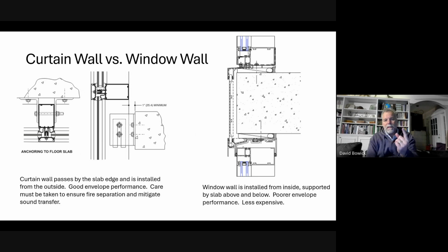You see the upper glazing above the mullion in the curtain wall system? Is it clearly an IGU, an insulated glazed unit with an airspace? That's an insulated condition. Below that, you see only a single glazing, which might imply that we have single glazing there and it's a cold problem.